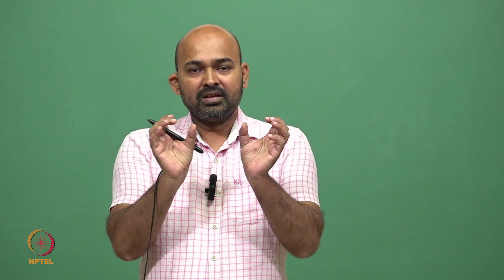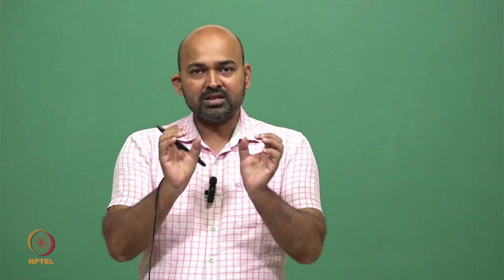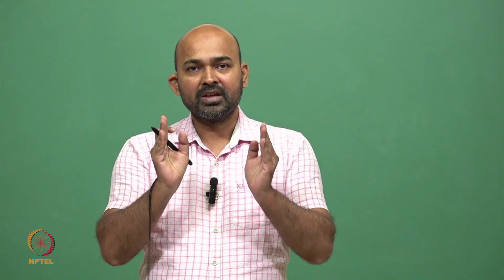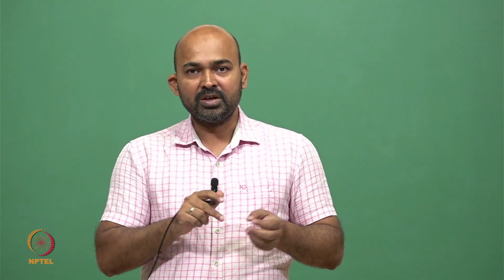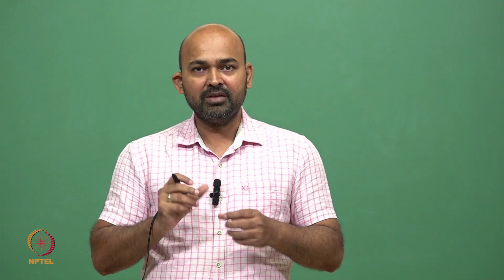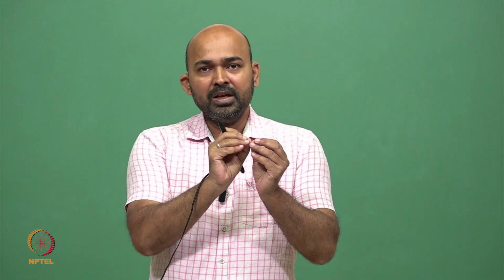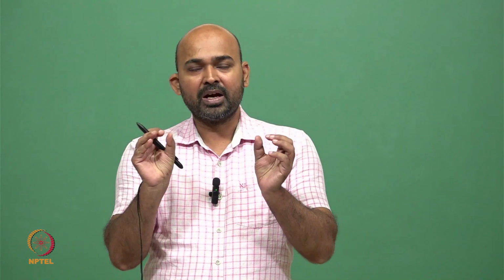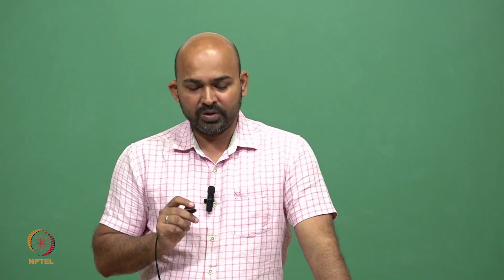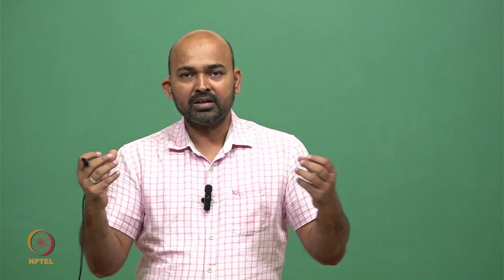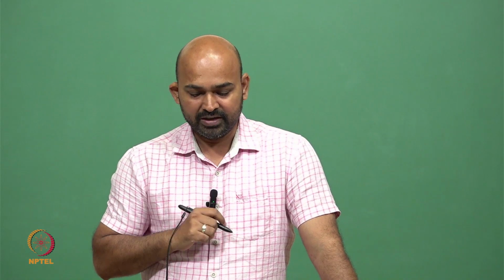When we see these two signals, the applied and the received, they will be delayed in time, and that delay will be twice the distance between IDT and reflector divided by the velocity. So these two signals will be displaced by that time delay, and this is called the SAW resonator. It is a kind of resonator where the acoustic wave is bouncing back to the same IDT.